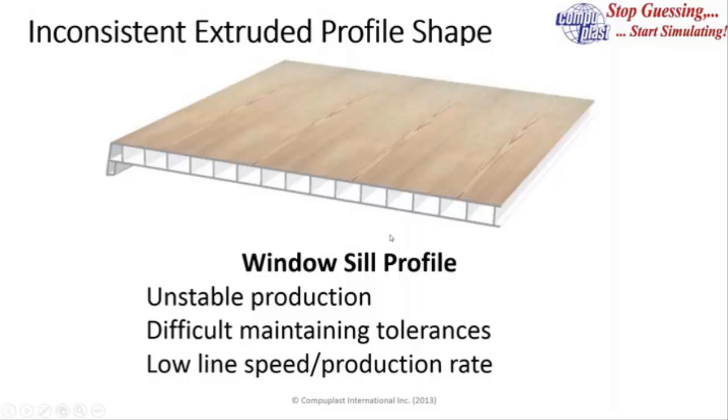And one of the issues was that they said, okay, well, if we can't go faster, let's build another line. Let's put another line up with the same geometry. And the traditional approach in profile die design is cut and try. When they ship the die initially, they usually ship it with a tuner, someone that goes along to the plant with a file and maybe some local machining equipment and makes modifications to tune in the geometry.